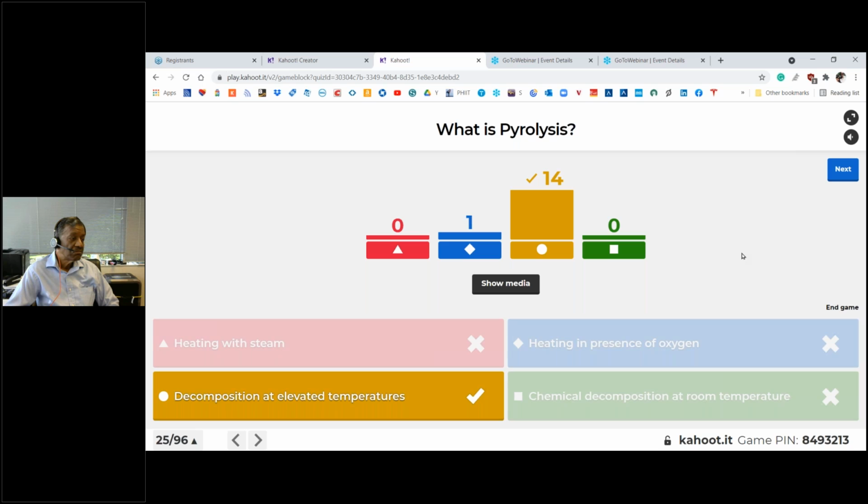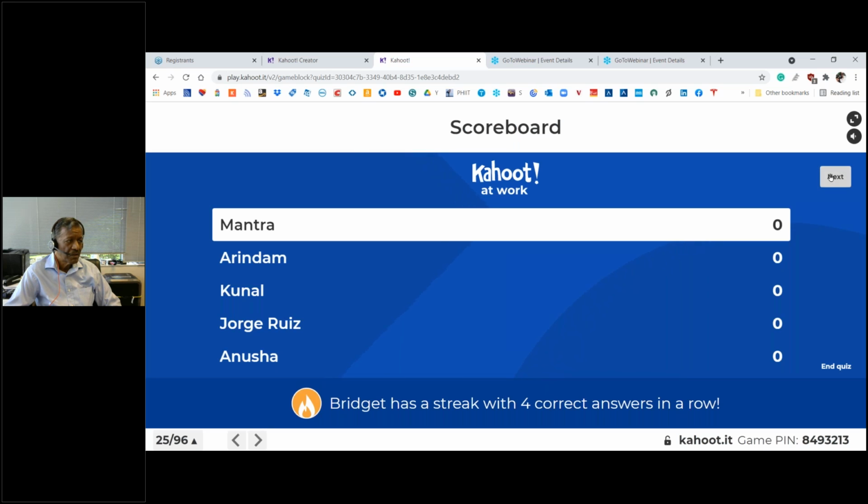It's mostly done in the presence of steam. Dilution steam, although it does not take any part in the chemical reaction, does help in improving the yield of ethylene by reducing partial pressure, as well as in coking. So it does help. So that is the basic pyrolysis, what is taking place inside the radiant coils where the reaction is taking place.